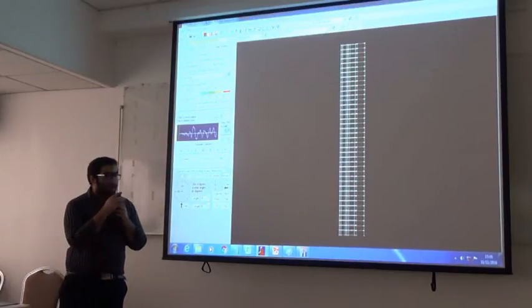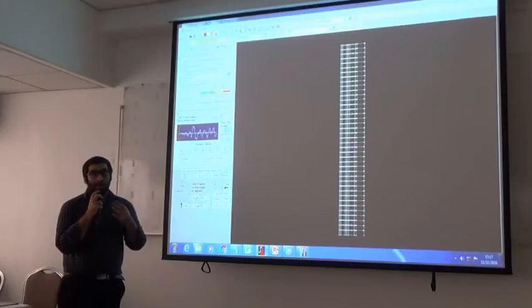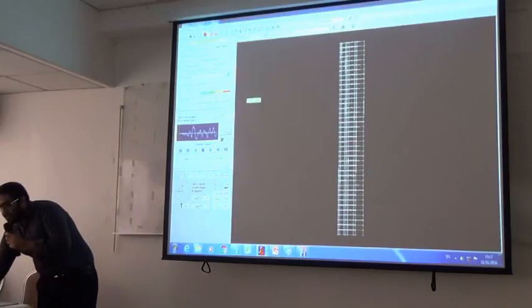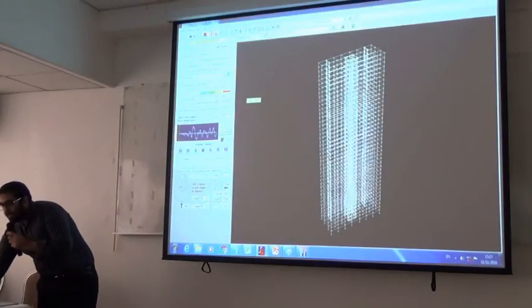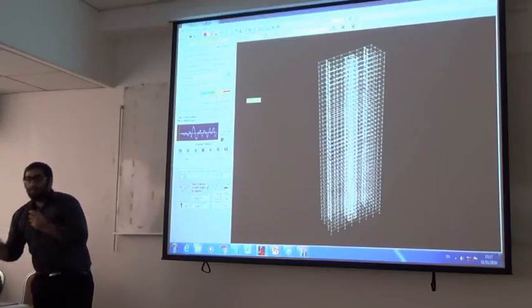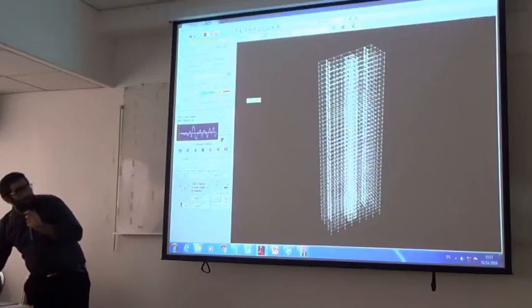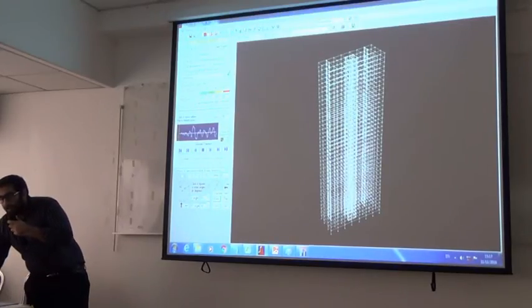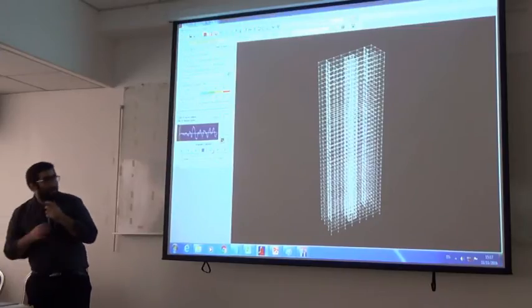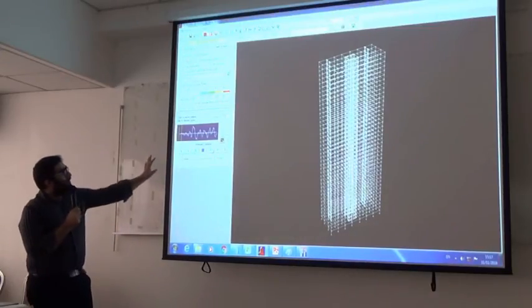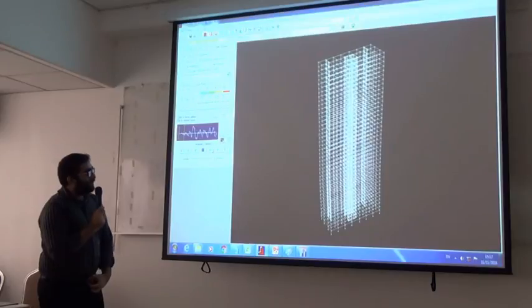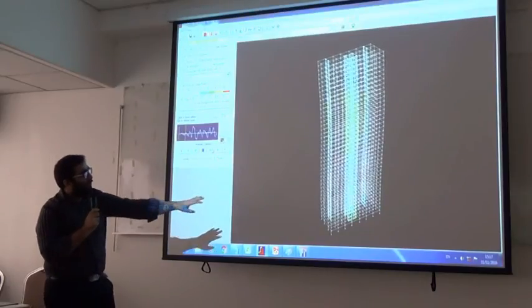spoke about the previous strain gauges that we had assigned to the model to check the performance of the wall, I had discussed that we already put some strain gauges which will give us the value for the DC ratio of the strain, right? Now the DC ratio for this plot being used is the steel strain DC ratio or the tensile strain DC ratio, right? And if I will continue the plot, now this is the deformation of the structure as the ground motion is progressing. You will see that after a certain amount of time, the colors are already forming in the strain gauges.